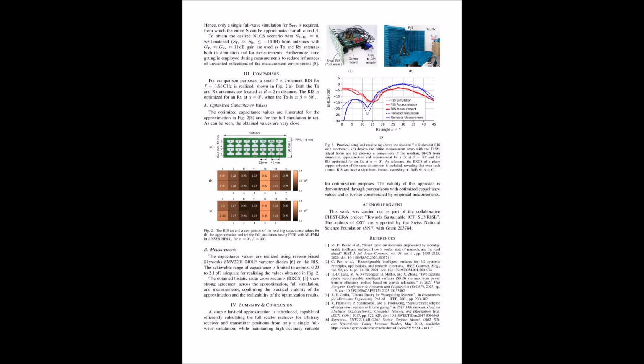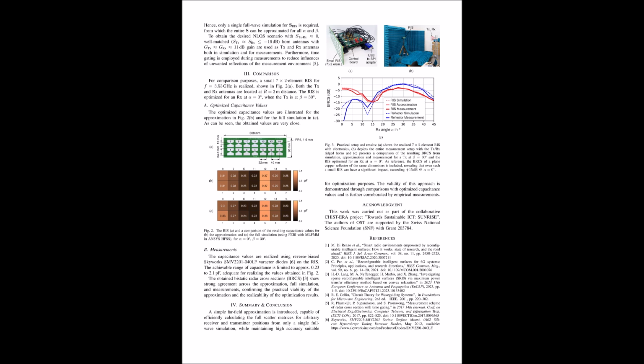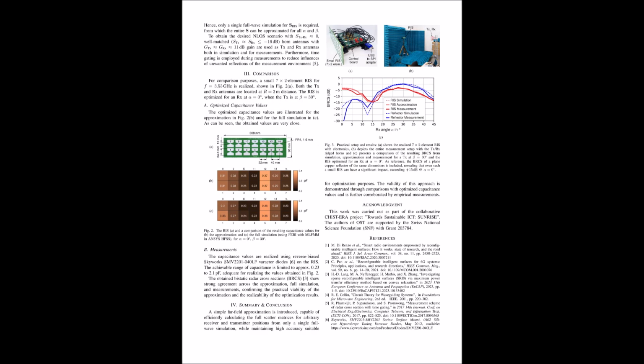And a mismatch in impedance means there's going to be some signal loss at that interface. That's exactly it. And this first term in equation 1 is accounting for that potential loss due to impedance mismatch on the RIS side. They assume the transmitter and receiver antennas are perfectly matched. So we're really focusing on how well the RIS is accepting the signal from the transmitter and then retransmitting it to the receiver. So the smaller the impedance mismatch, the closer this whole term gets to 1, meaning less signal loss. What's next in this equation?